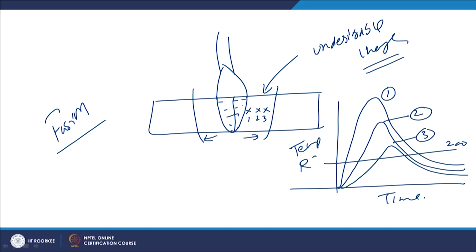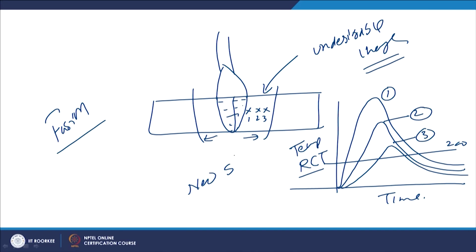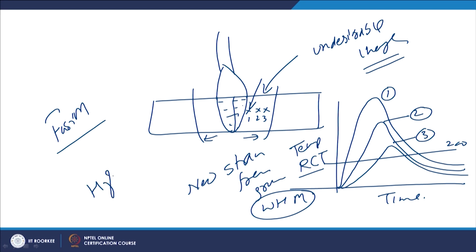So, say this is the recrystallization temperature, and as soon as the metal is exposed to a temperature above this temperature, it will experience recrystallization by formation of new strain free grains in the case of work hardened metals. So, the regions which are very close to the fusion boundary in the case of work hardened metals will experience very high temperature, and that too for a longer period. This is what is evident from this diagram.